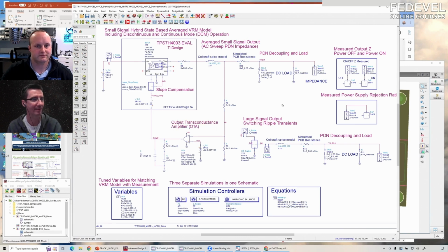And you can explain these other parts. So then you have your feedback loop. This should make sense to most power supply designers. You have a feedback network, setting a resistor divider to your error amplifier, which is inside. All of this is usually inside the VRM, inside the device. Here's our error amplifier, which in most buck regulators today, most IC designers at ADI or TI or Renesas, are going to use a transconductance amplifier. They're cheap, right? And that's what this is.